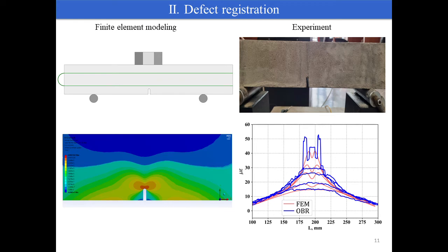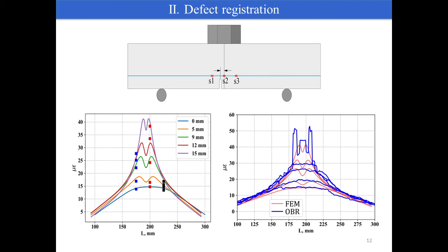During the experiment, the length of the cut was increased from 5 to 15 millimeters in several stages, and the sample was loaded with the force of 403 newtons according to the scheme. Analysis of results obtained by distributed FOSs showed that the location of the crack shifted from the center along the length of the sample. The point FOS also proved this statement. Since the introduced defect is located between sensor 1 and sensor 2 of point sensors, sensor 1 also effectively registers the appearance and growth of the defect, while the readings of sensor 3 are weakly dependent on the defect appearance and growth in this size.